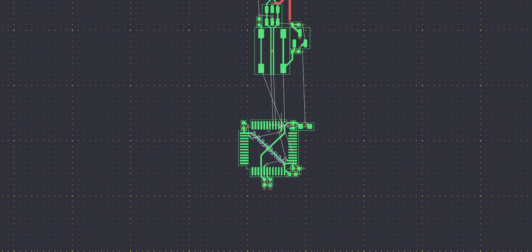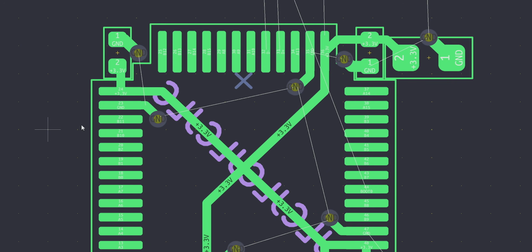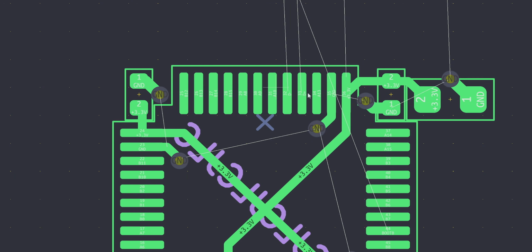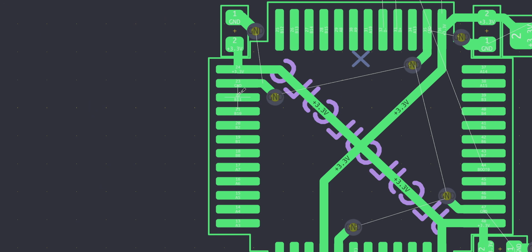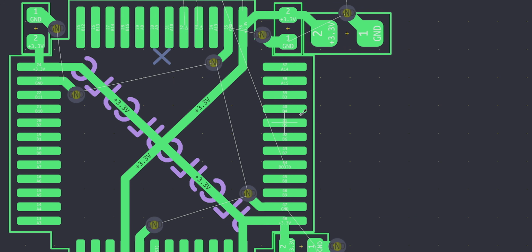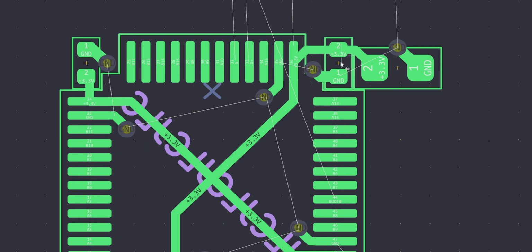So before we actually connect this stuff to the MCU, I want to run over what we have on the MCU here. The MCU is super simple. We just have all our GPIO exposed on the sides here. That was a consideration for this module I really took into account, that I wanted the GPIO to be really easily accessible. So you can see pretty much every area on this, I keep them as easily accessible as possible so you can get a lot of data lines out of this if I start running those. But the moral of this is that I want the left and right to be the primary GPIOs. So we have all these exposed on the side, and then these are all our decoupling capacitors.